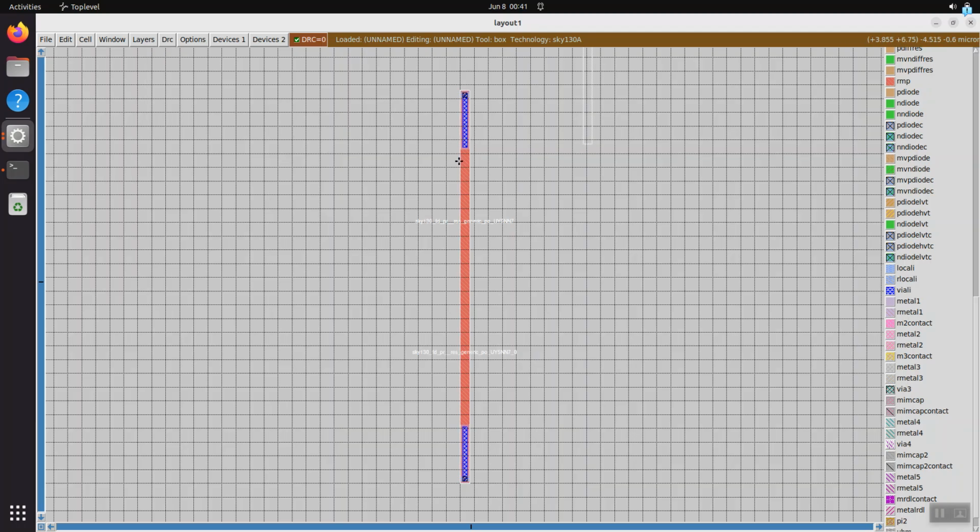Okay. So in order to more easily, if I start selecting things, I want to copy the whole thing, right? It's giving me all that. So I kind of need to go up one layer of abstraction. So if I don't hover over anything and I just select, it selects everything. Then Shift X, now it's a cell. And I can copy.